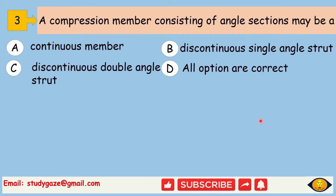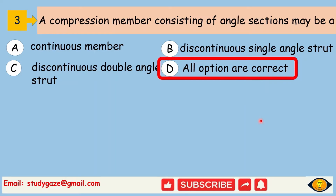Next, a compression member consisting of angle sections may be a... The correct option is all options are correct. It is a continuous member also, a discontinuous single strut also, and a discontinuous double angle strut also.